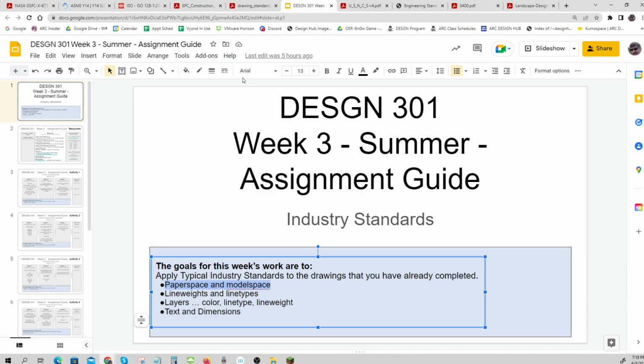And then you'll find that many of these standards talk about how heavy a line should be or how light a line should be. That's called line weights. And then different line types are used to signify different things. In architecture, there's thick, medium, thin, and far. In mechanical, there's object, hidden, center, phantom. In landscaping, there's irrigation, gas, border, grass.